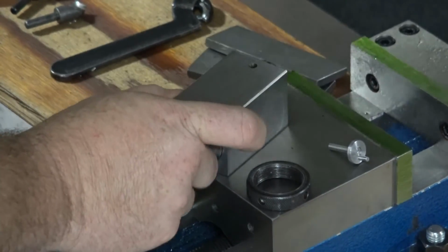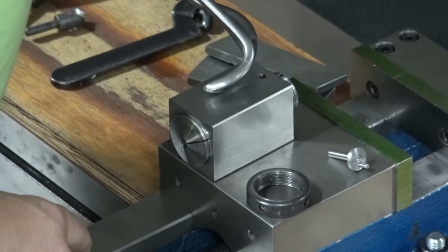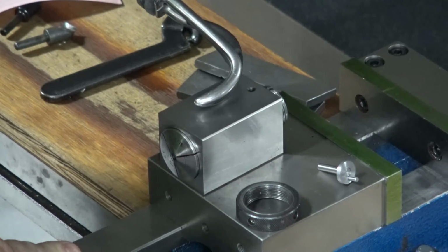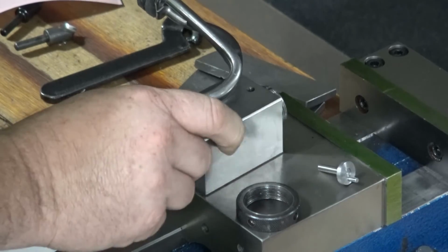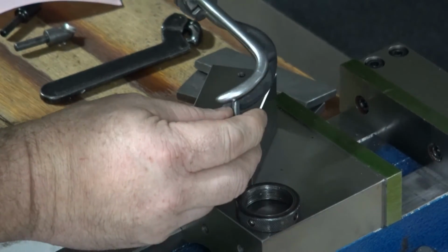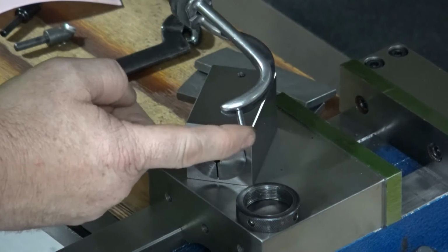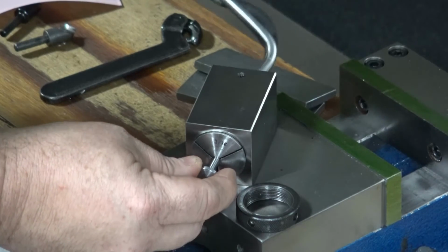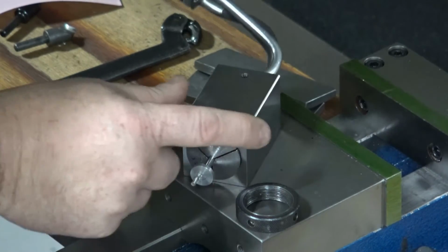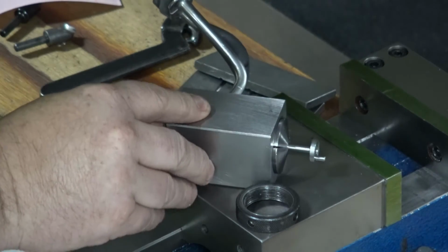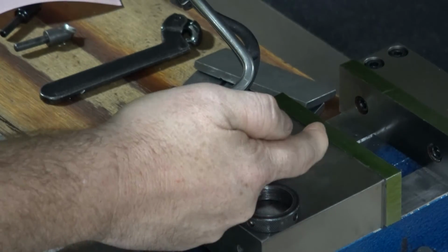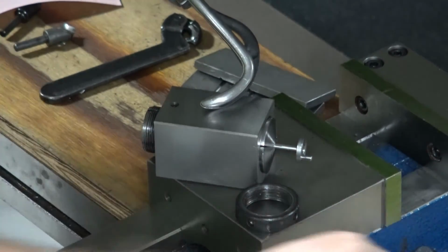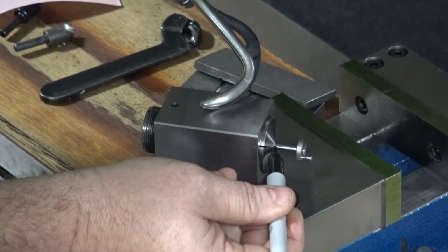Okay? So we've already done some calculation during our whiteboard exercise that I would like to have at least my 710 thousandths of length from the face of the crankshaft back to where I'm clamping. So if I just lightly put this in here, that means that I want at least 710 thousandths from this face to where I'm clamped on, right? Where I'm clamped on right up here at the collet end.